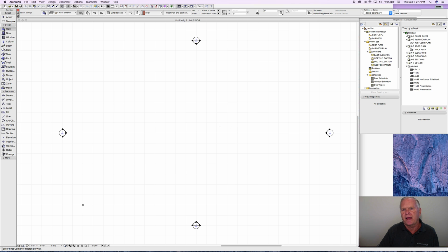Next, and last, is the wall thickness, and we're going to make this 1 foot because we're going to be doing exterior walls, and I'm planning on brick veneer and 2x6 stud wall. So we'll slide over here and get started with some walls.